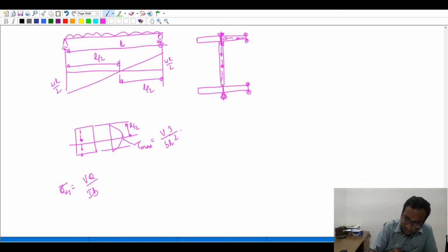Okay, now how will this resist the vertical shear coming on the cross section? Vertical shear will be resisted by the web alone. The flanges will be subjected to only the horizontal shear stress, like this. This shear stress flows like water, right? So if I were to put water on from this end and from this end, it flows like this through the web and goes over to this flange like this, goes out like that, right? So that's why it's called a shear flow.